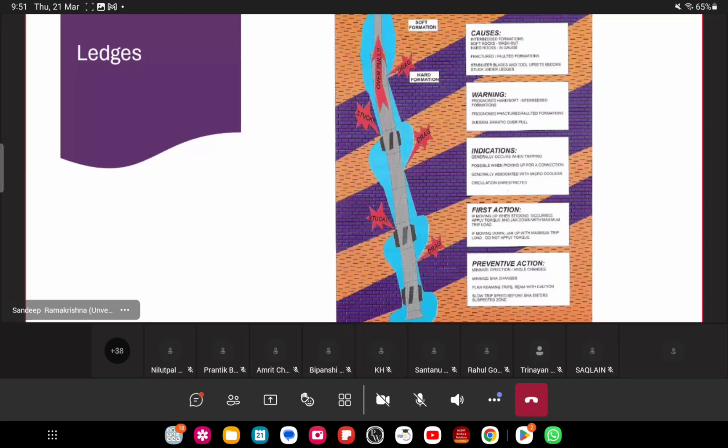Typically, you see that you struggle to move the drill pipe, and many a times you have to come back and ream these ledges out because it's not permitting lowering the string again. So you got to have some kind of a reamer in your string, and you're constantly having to work back and forth to ream the wellbore.